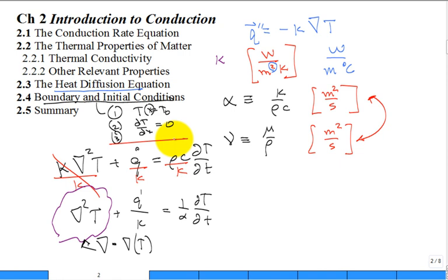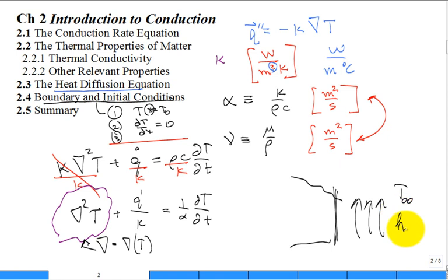It's a convection boundary condition. And so what we'll have is a slab, a solid, over to this wall. And at this wall, on the other side of the wall, we have a convecting fluid characterized by temperature far away in the convecting fluid and a convection coefficient. And what we do is introduce a very thin little control volume at that wall, and we say, what flows in must flow out. And we have a little Q double prime conduction flowing in, and we have a little Q double prime